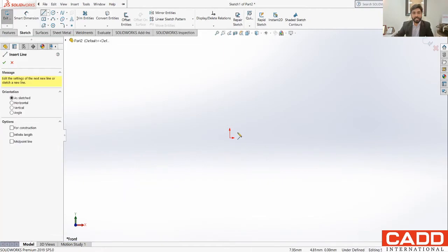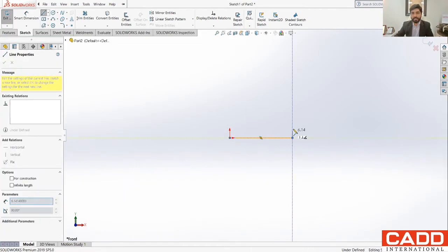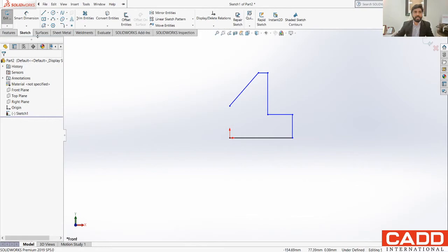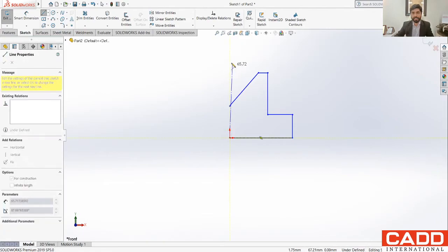I'm making only half of the contour. The exercise that we saw looks like this. When we are creating a line, when the line is horizontal or vertical, it will give you a snap. You can see near the pencil cursor a line inside a yellow box. It clearly suggests that your line is either horizontal or vertical. So you can create a contour in that particular shape. Here I have created the shape, and as it is symmetrical, I'm drawing a center line starting from this origin.